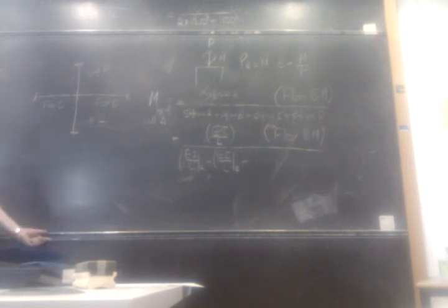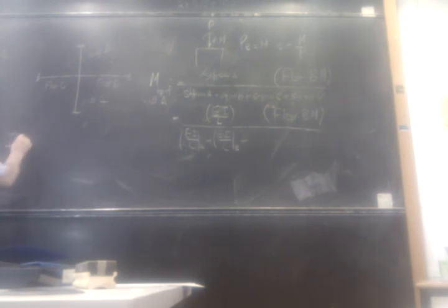We'll have L's in there. Were they the same? No, the L's are different. You've got a 3,000 in there, 2,850. I've just tried to make them practical dimensions. So the L's will stay in. So now we need the I. And again, I is BD cubed over 12. Slab's 150 thick. Walls were 150 thick as well, I think.